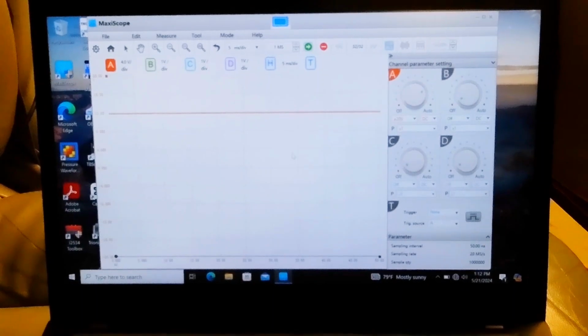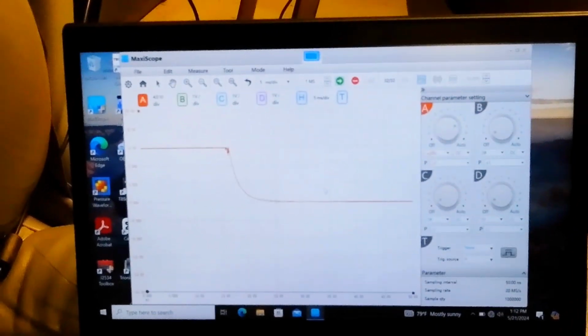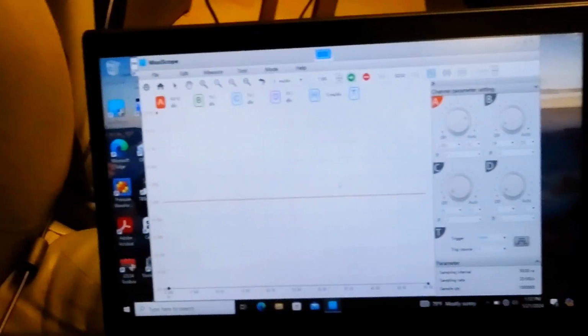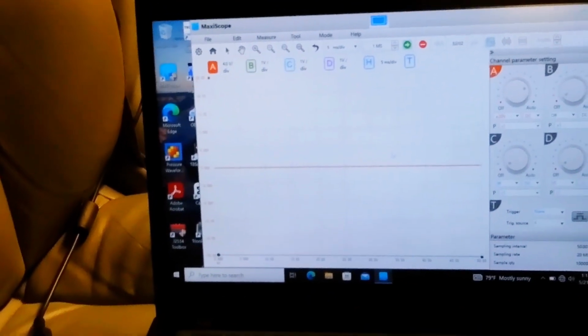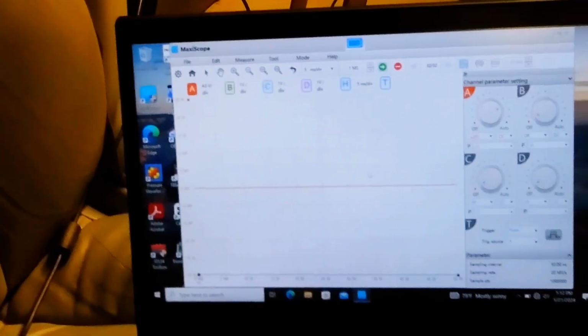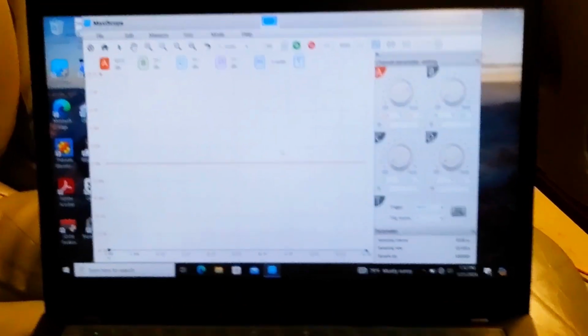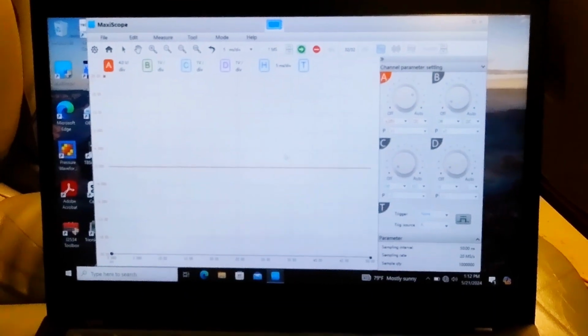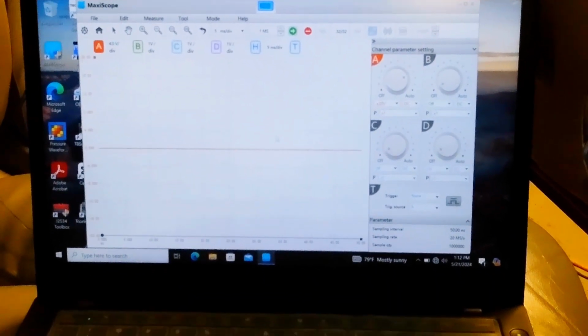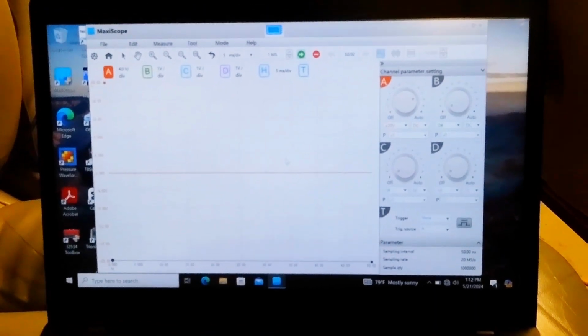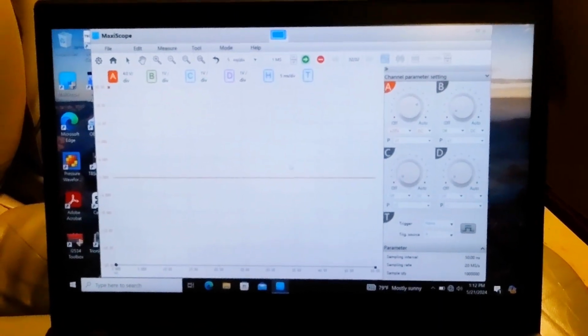The module itself is grounded at pin A. So we're going to check pin A and see if the module has a good ground. And it does, good clean ground. So we're going to also check our variable pulse width signal that is coming from the HVAC control module to tell this module to turn on. That is on pin B at the blower control module.